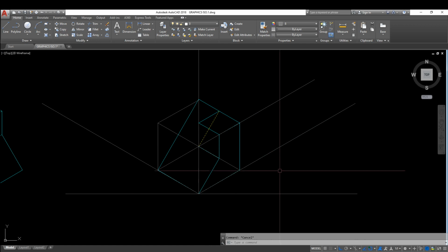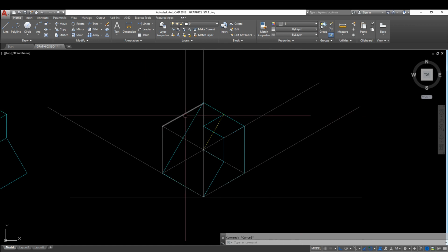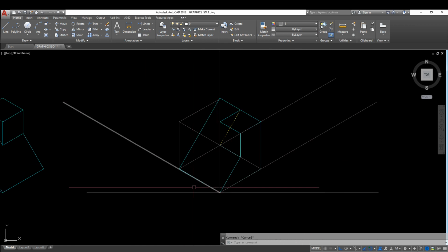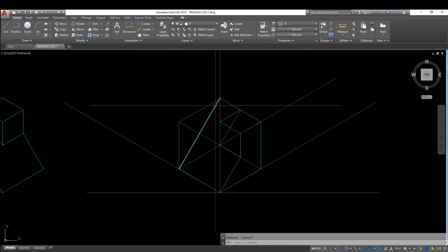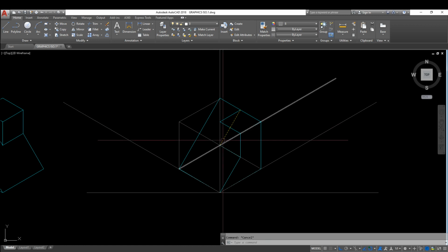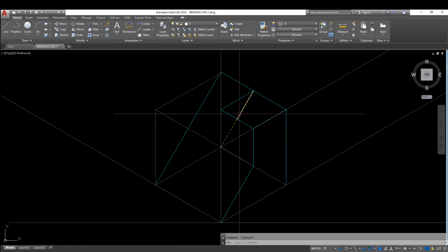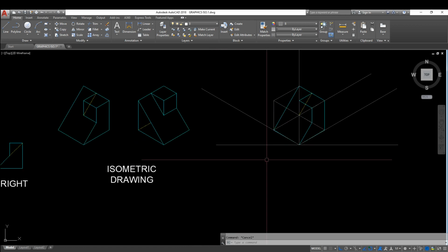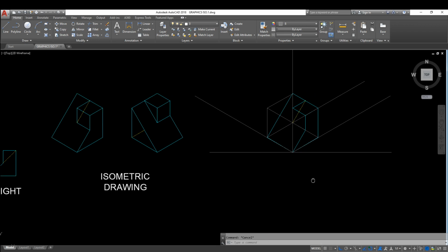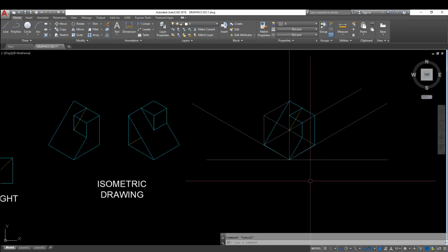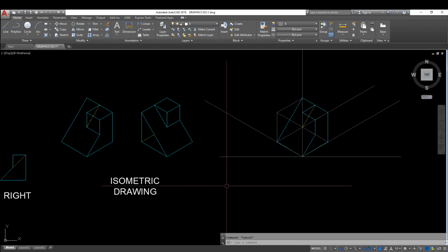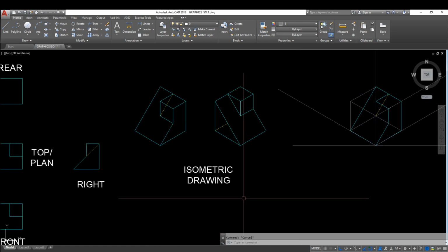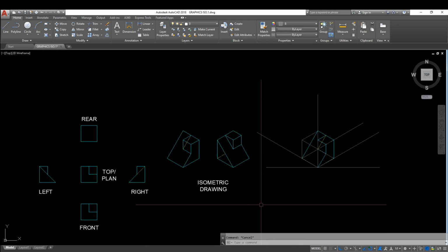Okay? So for example, when you establish guidelines in your isometric, just continue with a thin pencil, and then you will finalize using the unipin. You can use 0.5, and then 0.1 for the invisible lines. Okay? Buy two unipins. This is the unipin, it comes in different sizes. Same as the tech pen, but it is not a mechanical pen.